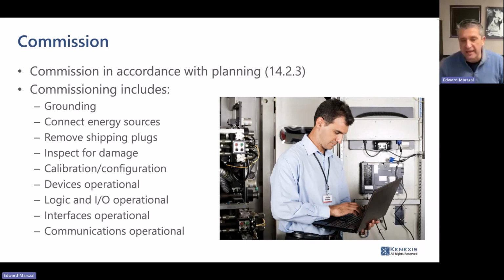So you know that the device is working based on your calibration device. You hook the Fluke up to it and everything checks out. But you also need to make sure that that signal travels to the right location and that the receivers are programmed properly. So you're going to want to make sure that the logic solver is operational and the I/O is operational by going into the maintenance and engineering interface. And when you're manipulating the sensor, you're going to want to look at what the signal is in the maintenance and engineering interface to make sure that the logic solver is correctly reading it.